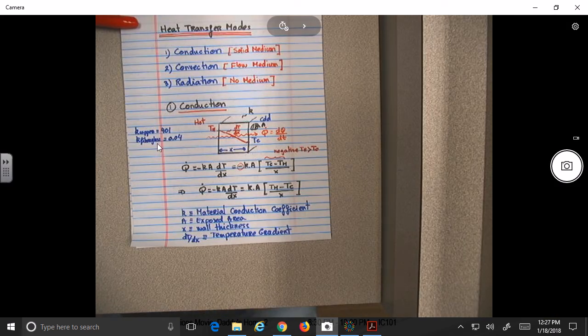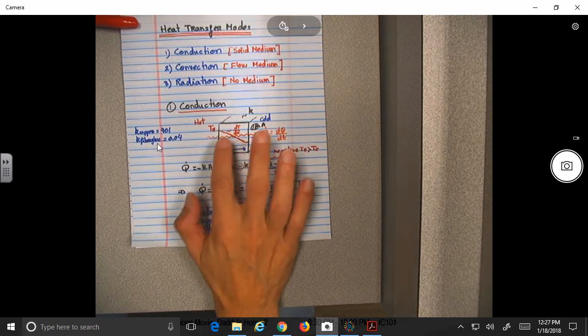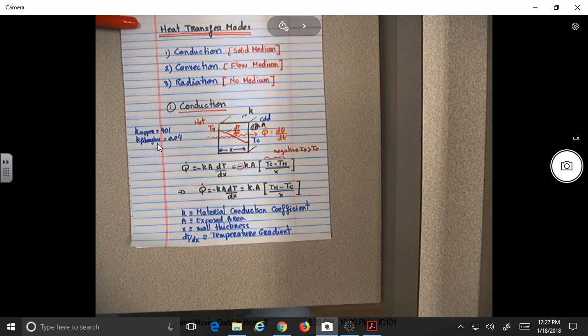So in order to conclude, can you stop the heat transfer? Can you stop the heat going through the wall? No, but what can you do? You can slow it down. If you slow it down enough time, the process is going to go the other way, no? But it's not something you can stop. It's something that you can slow down, and that's why you put insulation.